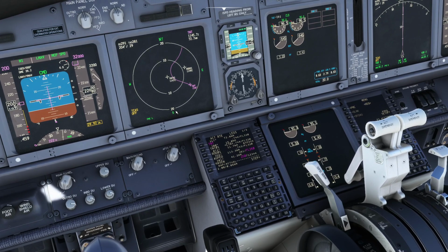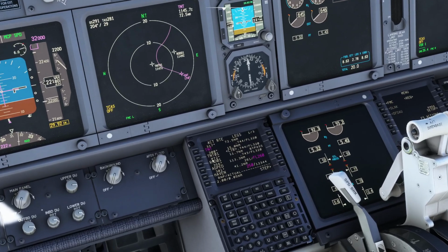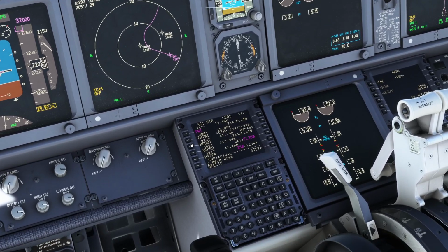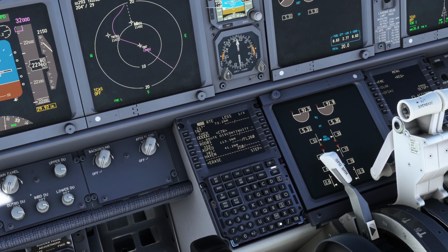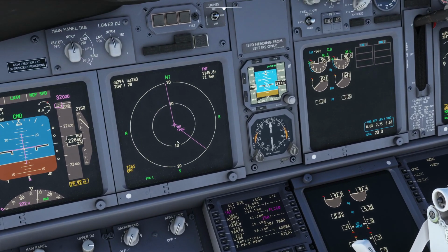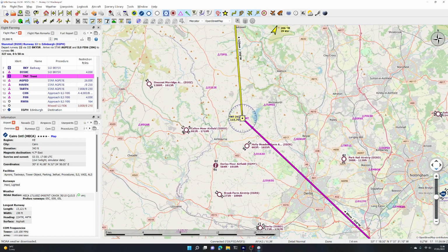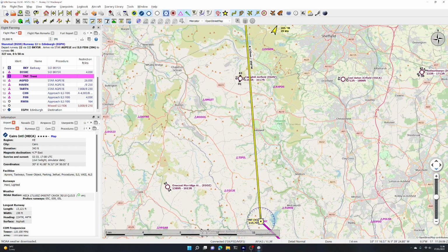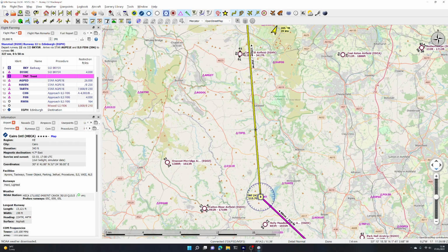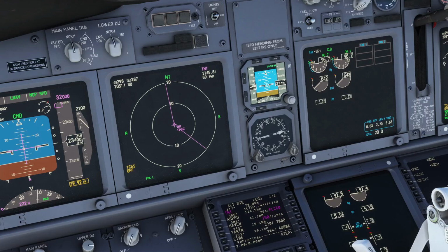Now, it gets even more clever than that. So let's go and remove these ones, because we're not actually going to use it. Delete, and delete, and close the gap up. So we've got rid of our custom waypoints. So we're back on the path we originally planned. What if, leaving TNT, we wanted to fly through a point on this route that we're flying along that passes Tipil, but we need to put an entry point in here to maybe change direction at that point.